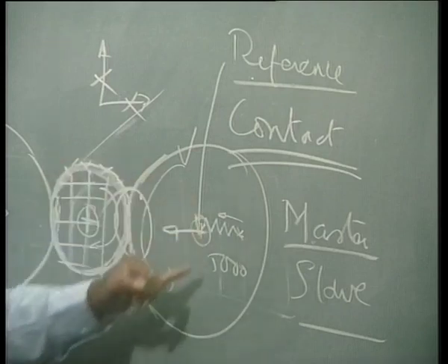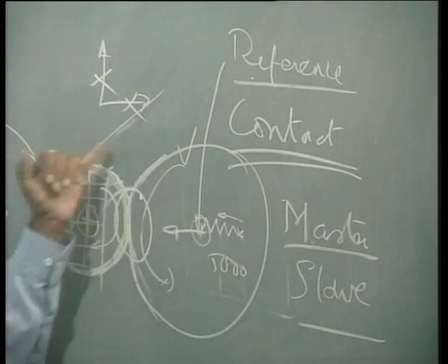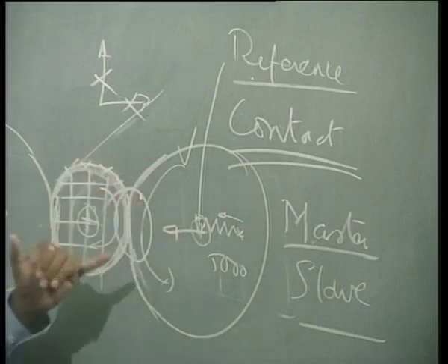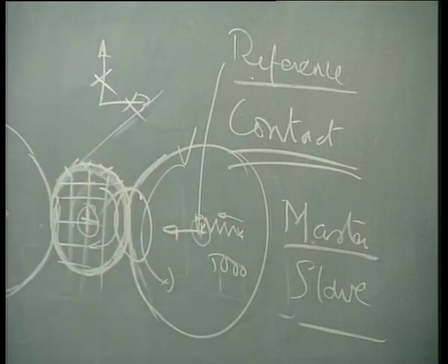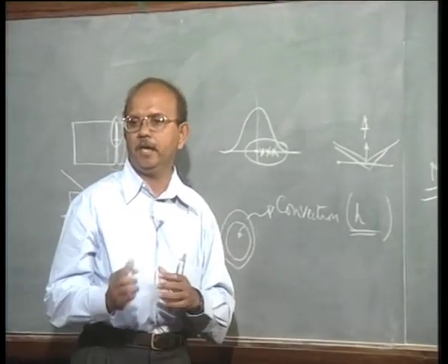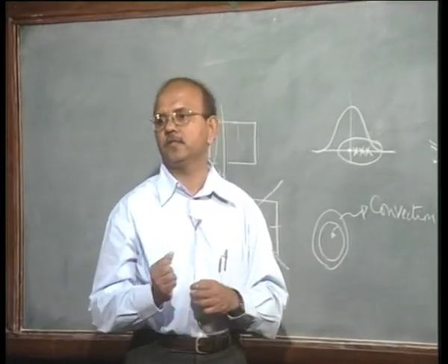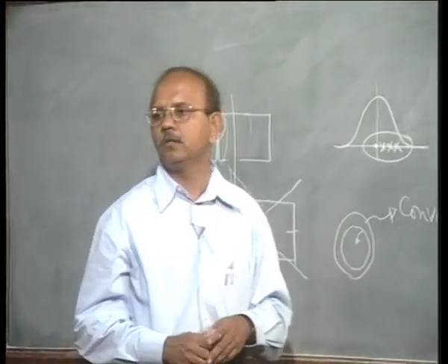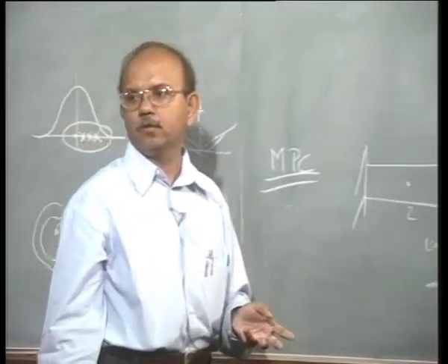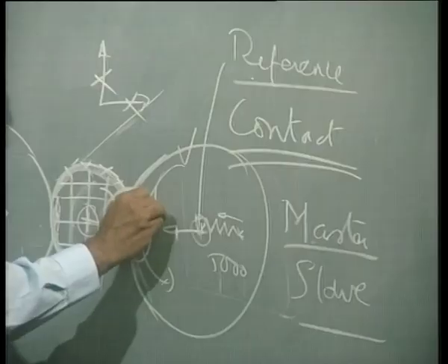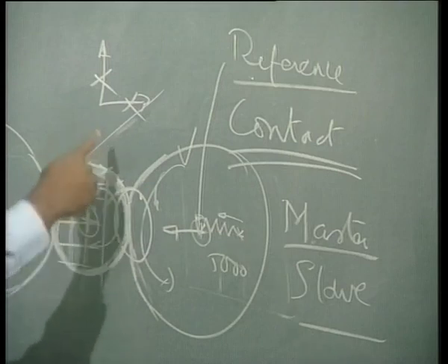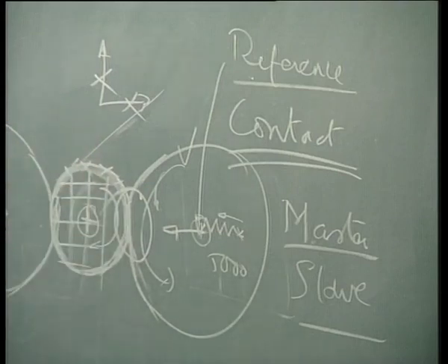Singularity will also be removed because this contact element would be considered completely as a system, with the contact element taking care of your singularity, because you will be putting some Kn, normal stiffness, tangential stiffness and so on, you will not have any problem. And when you start rotating, if the friction is good enough, this fellow will start rotating as well.